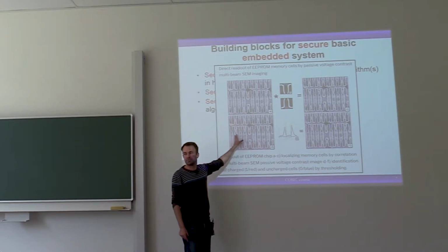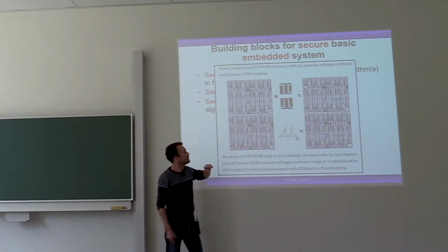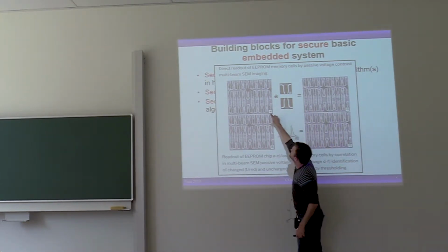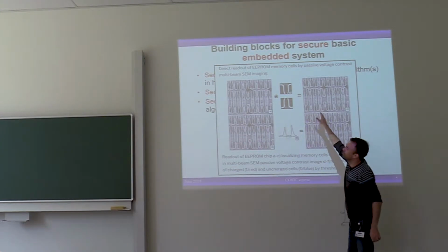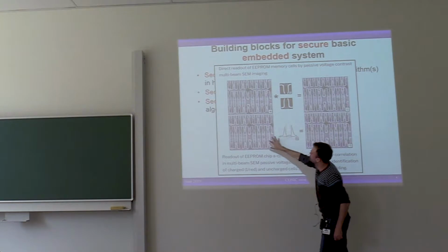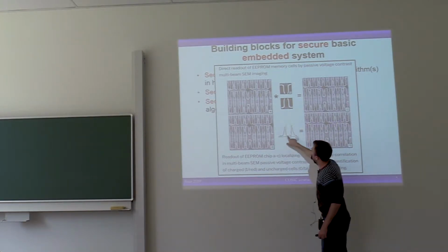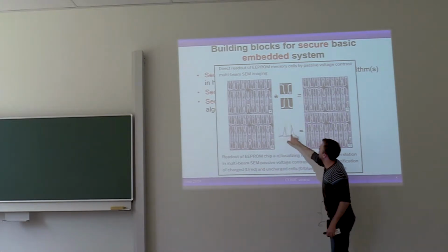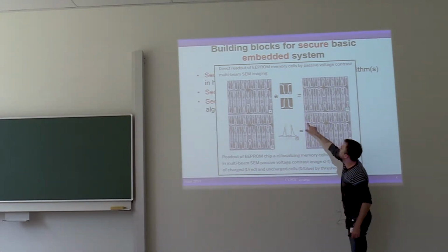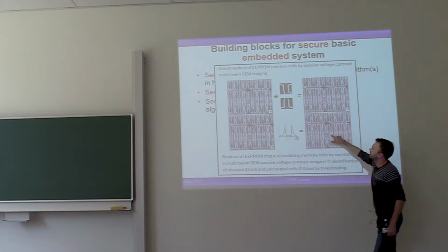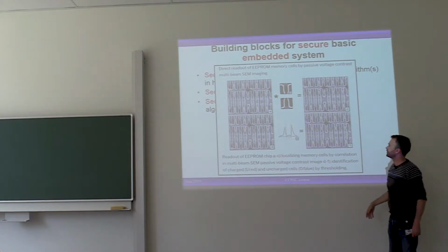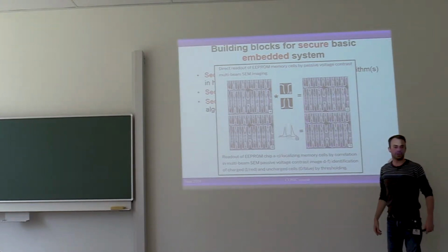And if I understand how this memory works, and if I understand what I'm looking for, I can essentially, so first of all, this image just shows how the person found the relevant memory cells, and these two images here show basically that there is a threshold in the coloring of certain areas, and if you find this threshold, then you can divide. So here 0, 1, 0, 1, and then basically you can read out bits, for example key bits, just from imaging the memory.